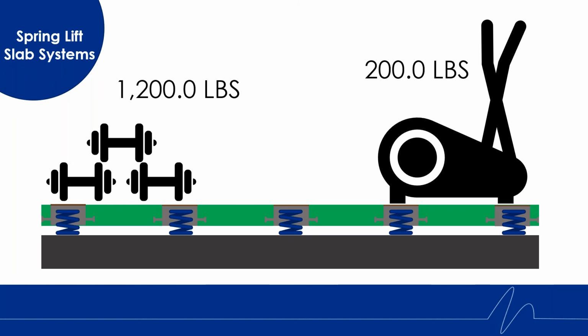During the design process, the Kinetics project coordinator will select the appropriate springs to support the appropriate equipment. In this instance, we would have divided that weight of 1200 among those two springs. So say around a 600-pound spring plus supporting the weight of the concrete. Then over on the right, we would have added an additional 100 pounds to the weight of the concrete and floor to the other LSM springs on the right.